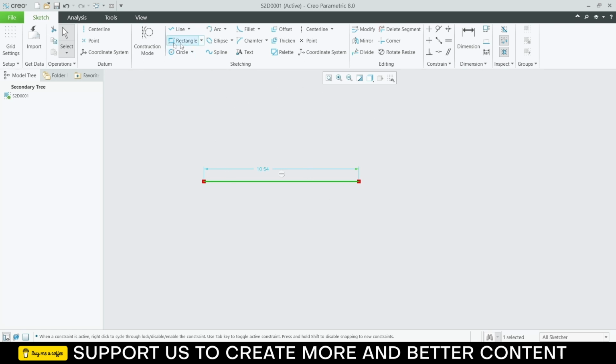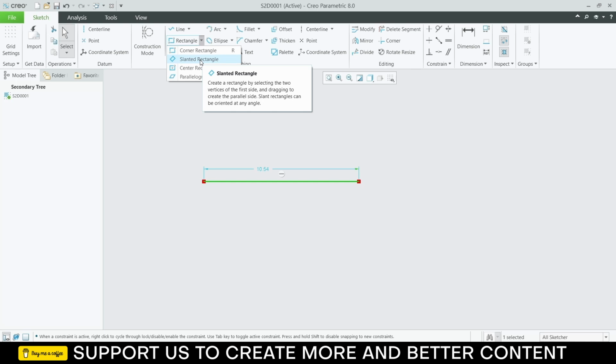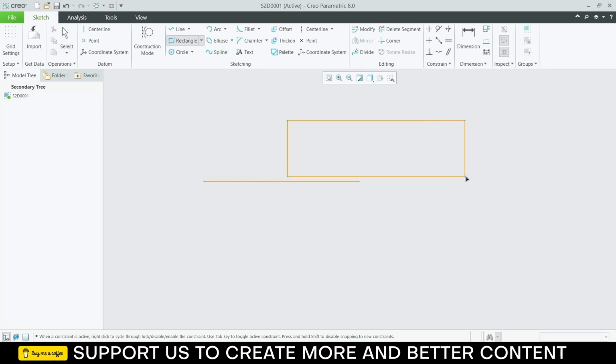Now let's try another command, that is rectangle. So in rectangle there are various kinds of rectangle: corner rectangle, slanted, center, parallelogram. So I will only talk about corner rectangle right now. About other rectangles you will only understand when we do practical applications, or in part and assembly, else you will not be able to understand what is going on. So I will click on corner rectangle and draw a rectangle here.